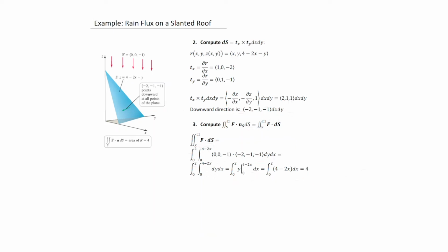All right, so this would be a mass flux. Okay, so mass flux would be in terms of kilograms per second per meter squared. That's the amount of rain that's hitting the surface, the flux density, and we would be computing it over the full surface area. So we'd be talking about kilograms per second of rain that has to be removed by the gutter system.